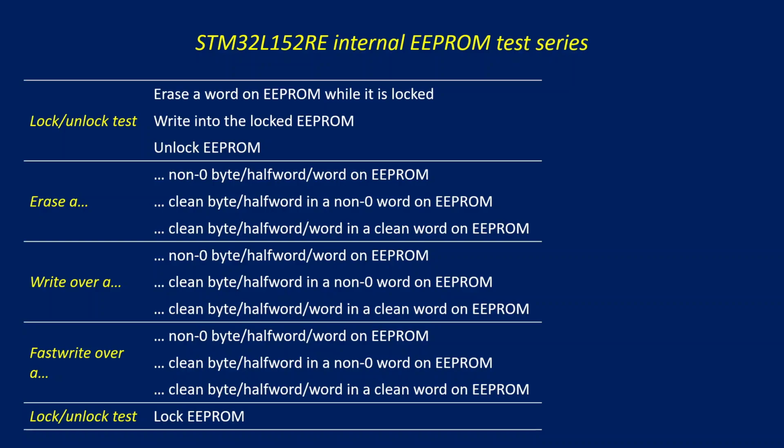I try to erase a word on the locked EEPROM. I try to write into the locked EEPROM, and then unlock the EEPROM. Then a series of tests in erasing the EEPROM content and writing into it, using the write and fast write commands. An operation will be repeated on an EEPROM location containing non-zero values,